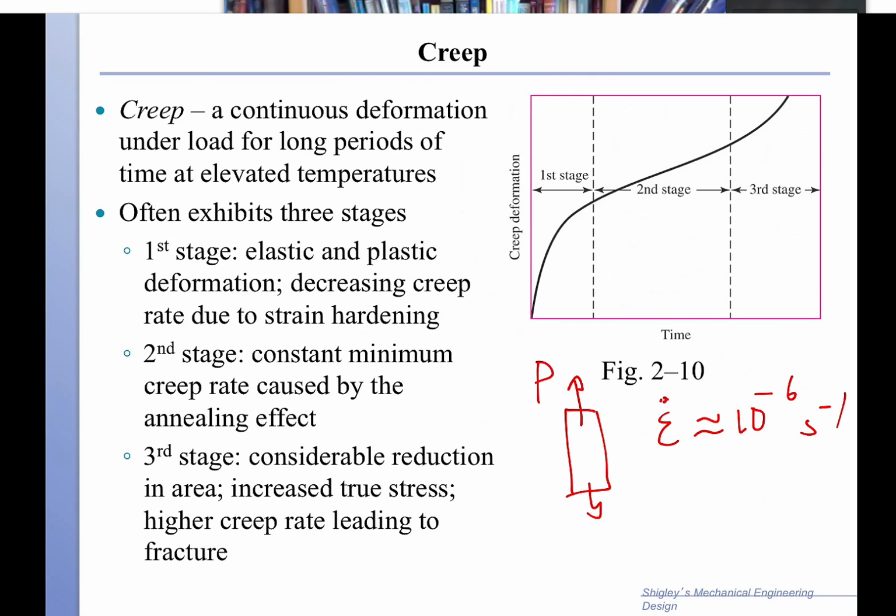So if I measure the deformation, which is delta L over L, as a function of time, then I find that the material actually will increase the creep. You get a little elastic part, and then it will increase very rapidly the deformation, and then it will go into a sort of continuously increasing linear phase, and then it will accelerate until you have fracture here at the end.